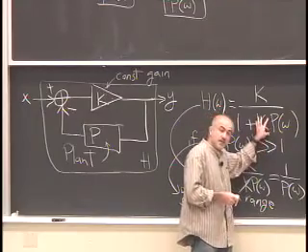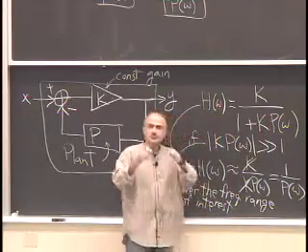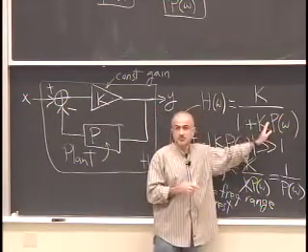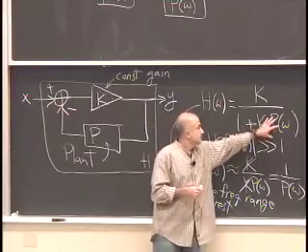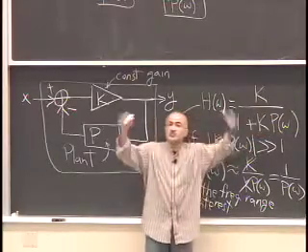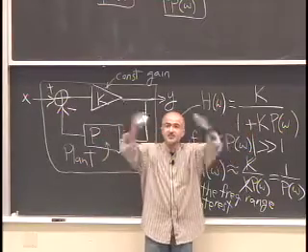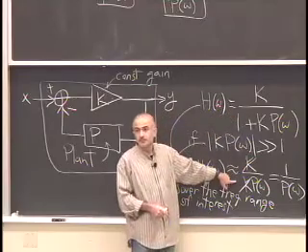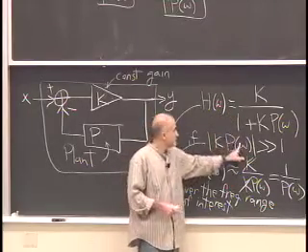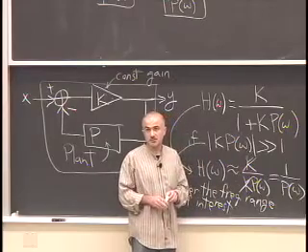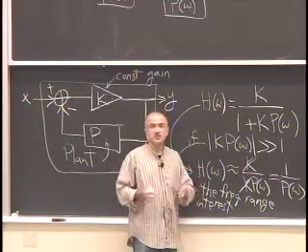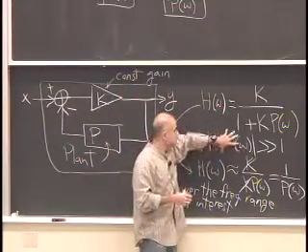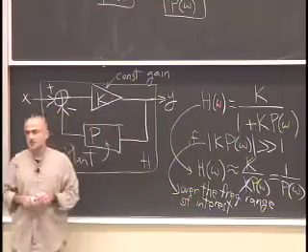So K over the range of frequencies needs to be high so that Kp is high. But it doesn't have to be flat, because the flatness of it is not what enables you to do the approximation from here to here. It's the fact that the product is much larger than 1 that enables you to do that. And that's what's great. So you can make it large and let it roll off. So what? As long as the product is large over the range of frequencies, you've designed your inverse system.